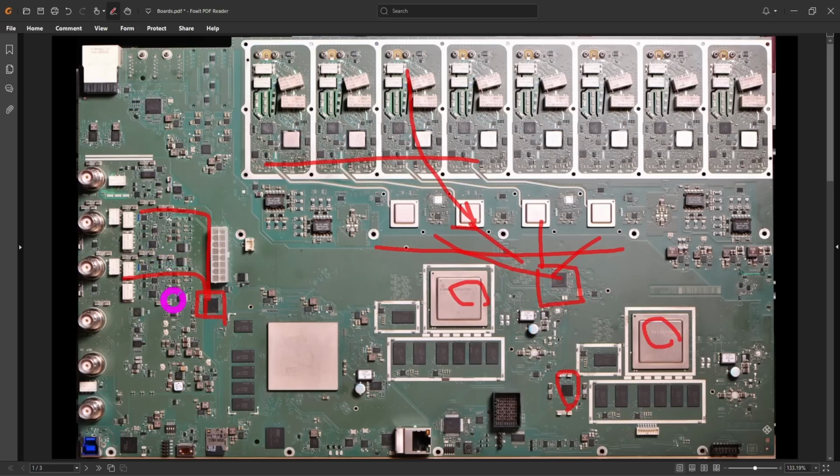Trigger input, reference input and output, and I think this DAC is directly driven from the Xilinx FPGA. Maybe this is its own dedicated memory, but either way, it's close to this for a reason. Everything else you see are either USB, Ethernet, controllers, and so on. Nothing unusual, a lot of digital parts.